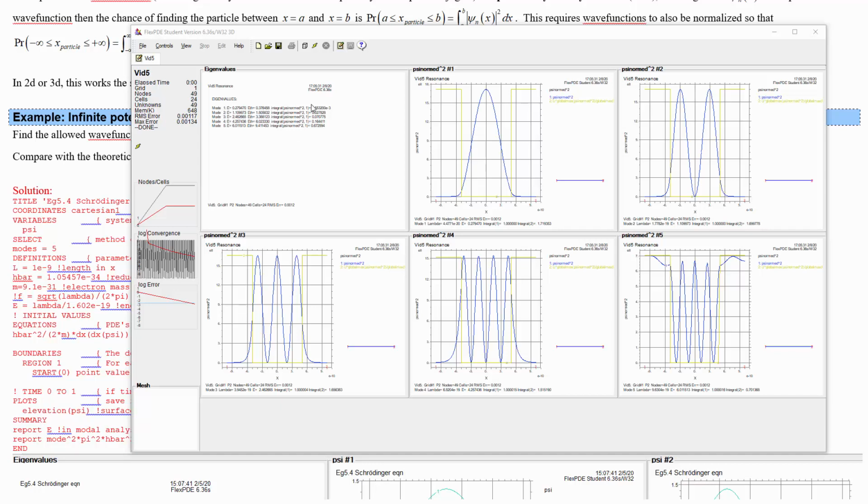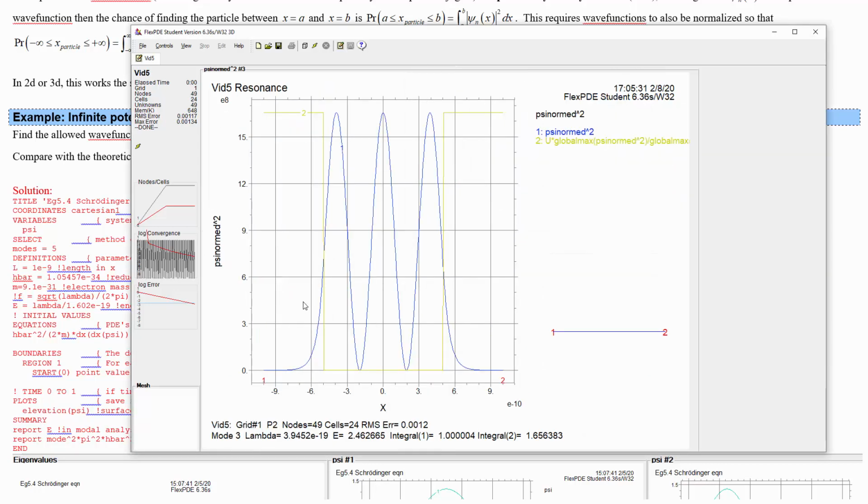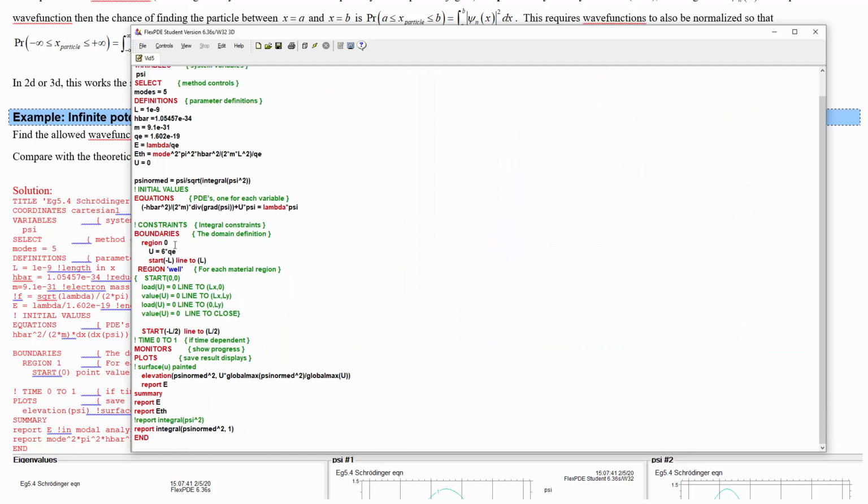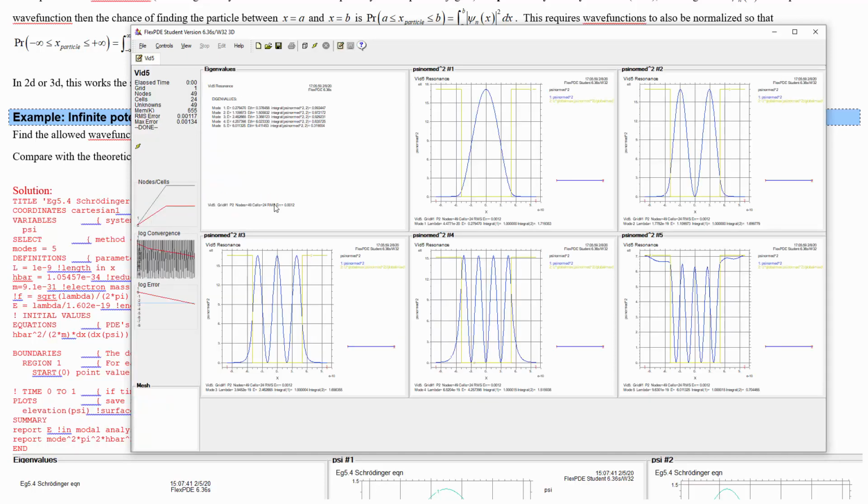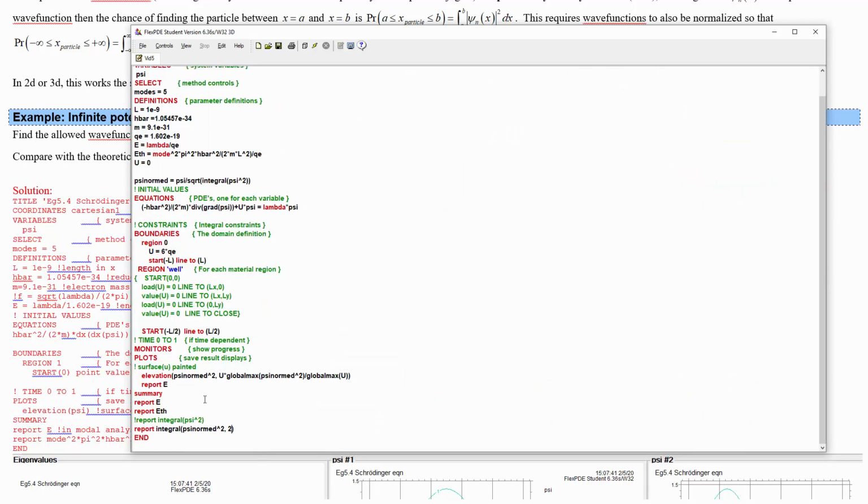It gives us over the first region. So 1 was the region that we happen to call 0, right? And this doesn't give us over region 1 or anything. It gives us over the region 0, confusingly. If we say 2, then it does the second region, which is the well. So because of this, it's better to not name your regions 0 and 1, or they're not going to match up with this default numbering syntax.